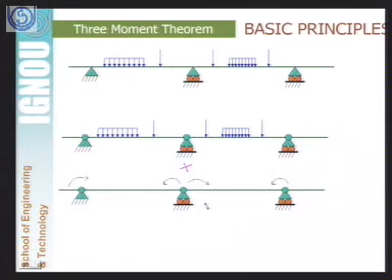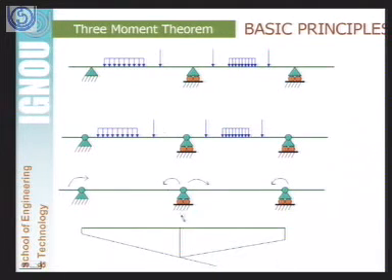And again if the supports are also sinking, then we can also add that here, and you can see that this is equal to this plus this plus this. So I will explain how: we have introduced releases at these nodes. This means that we have released the moments at these nodes.